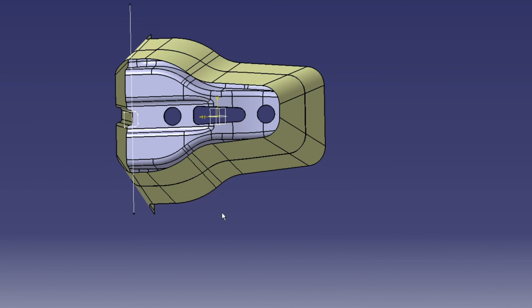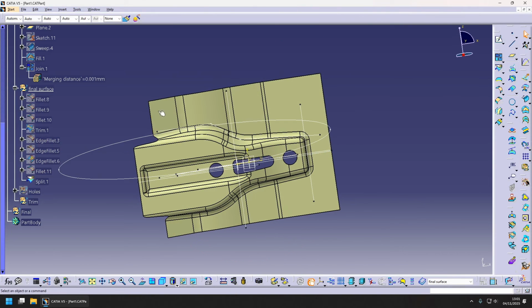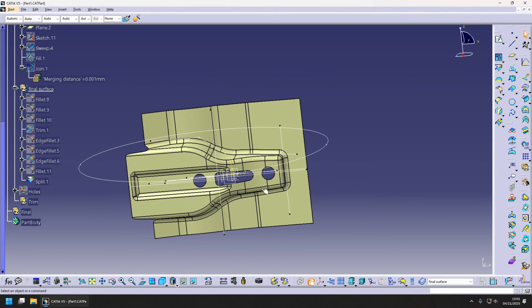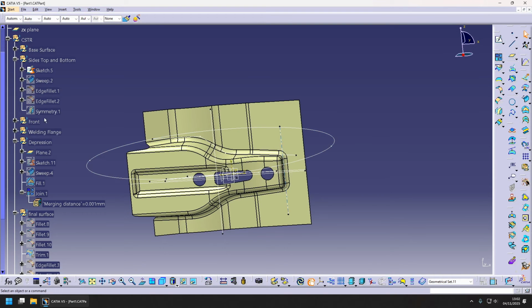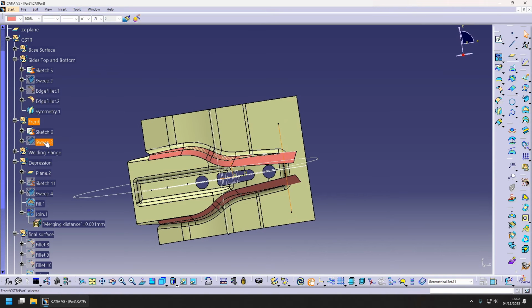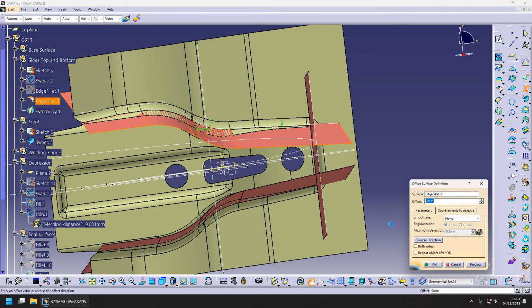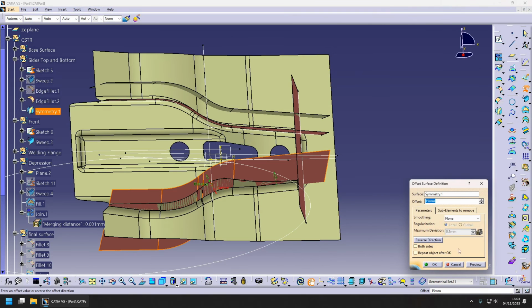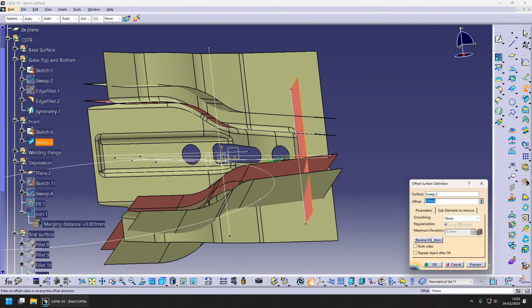And finally you have the trim. This will define your part's size. Now all that's left to do is the outer trim of the part. Go into the trim. For the trim, we are actually going to use the top and bottom sides and the front side. So first we do an offset. Let's say 15mm. 15mm this way and 15mm that way.